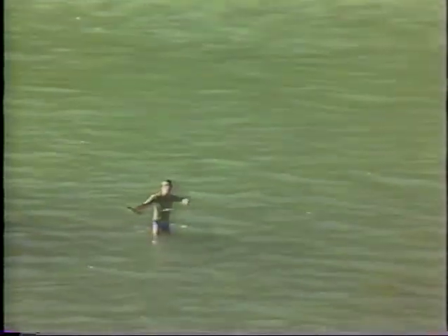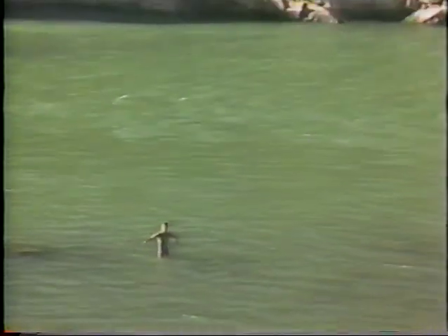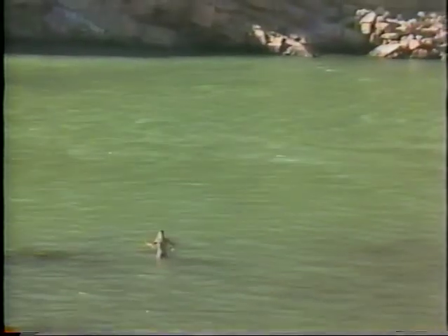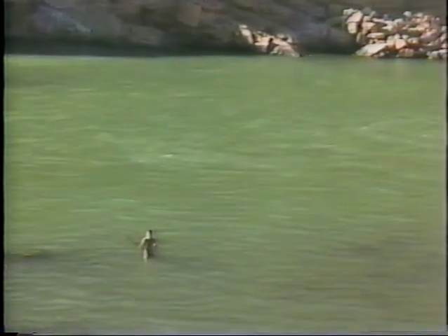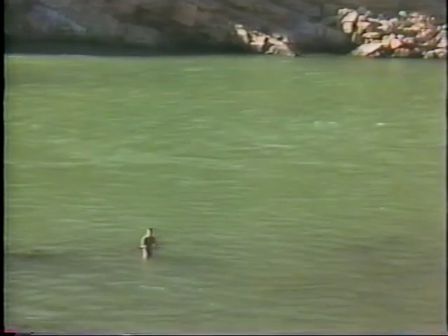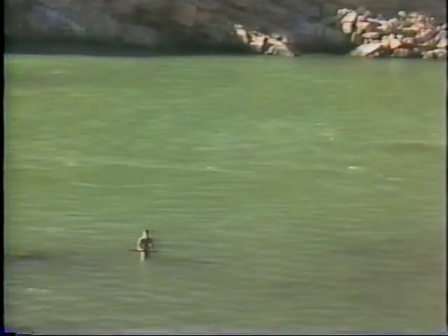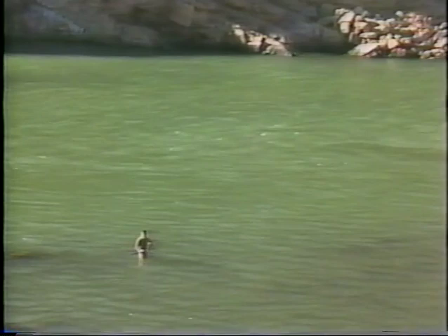Next you need to know the width and the length. You measure the width directly. The length, you don't measure the whole length of the river. What you do is measure a volume of water that moves over time. That's where you use the stick. So take the stick and throw it into the fastest part of the water like this.